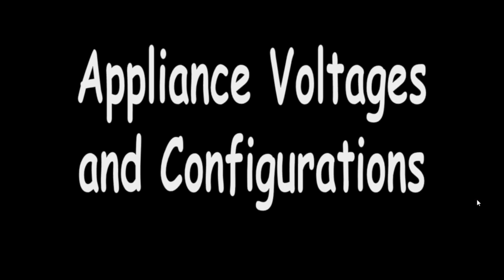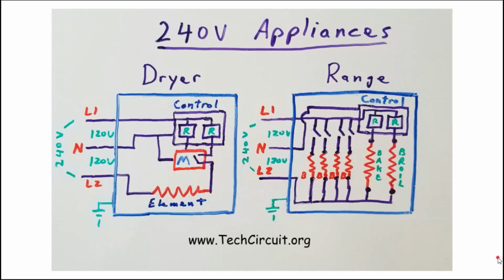Now let's talk a little bit about appliance voltages and configurations. In the United States, most 240 volt appliances adhere to a common arrangement in the way that they power loads and controls. 240 volts is advantageous for electric heating because, as we discussed previously, elements can produce 4 times as much heat at 240 volts than they can at 120 volts. An electric dryer primarily contains 2 120 volt circuits and 1 240 volt circuit.